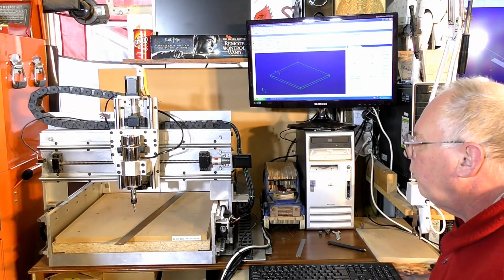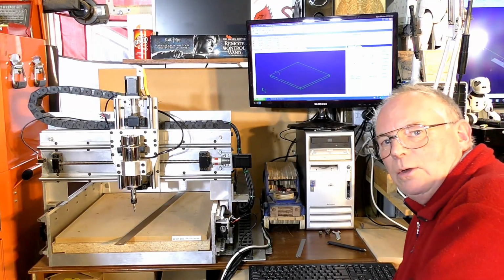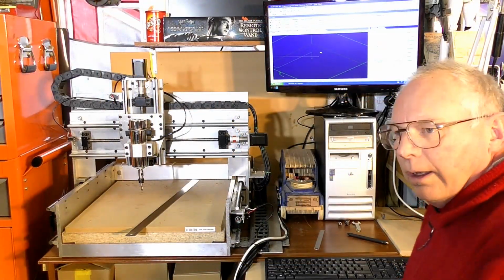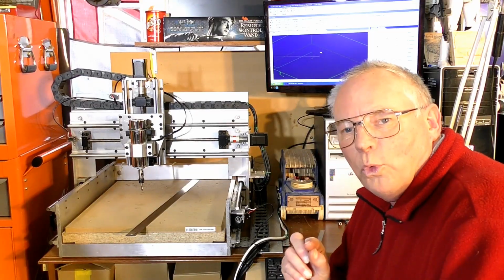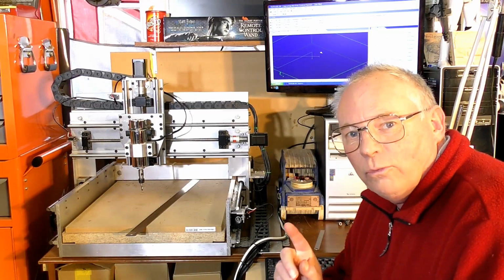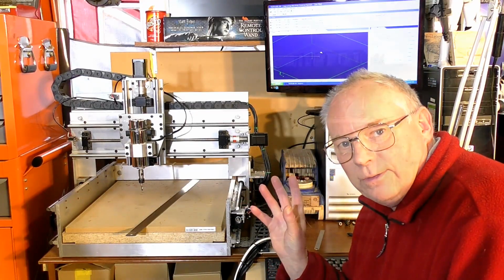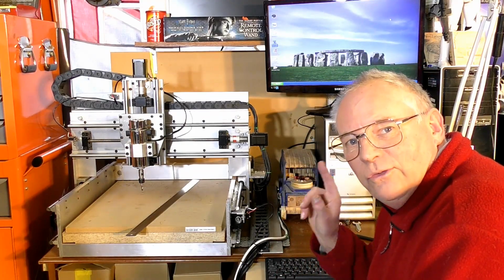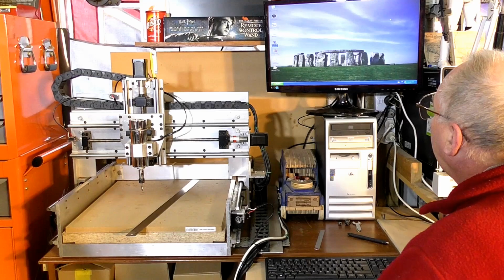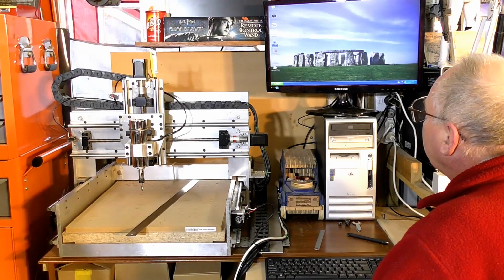Okay, so we're going to set an imaginary work offset now. And before I go any further, one very important step that you must do for everything to take effect, and that is to shut NC Studio down and restart it again.